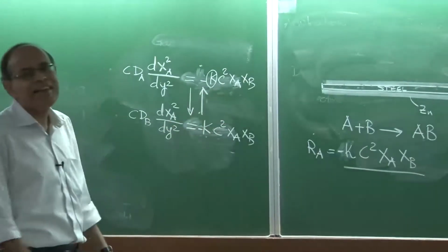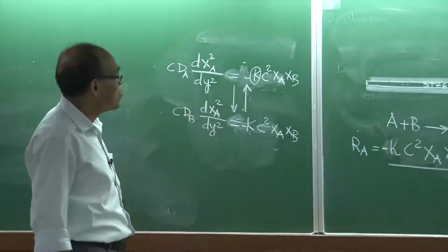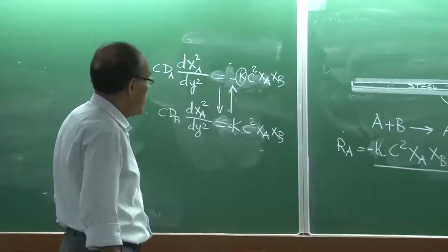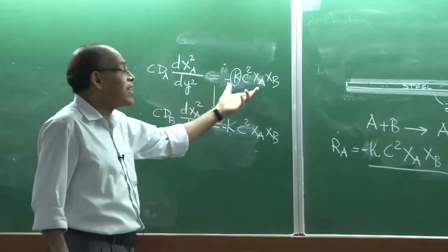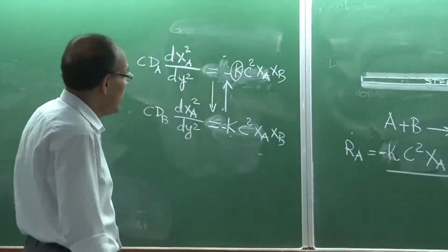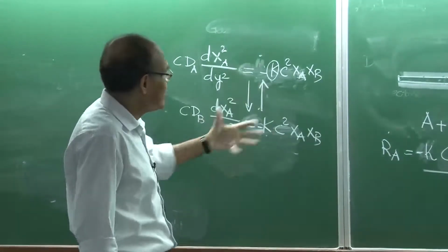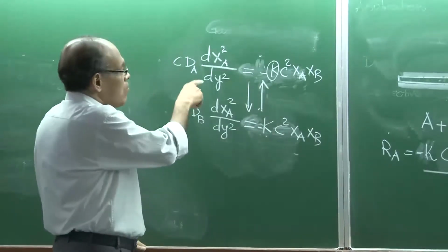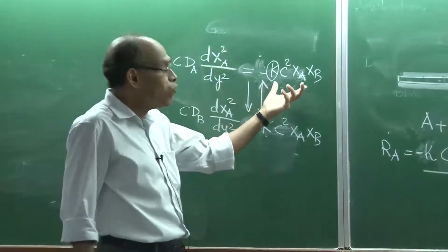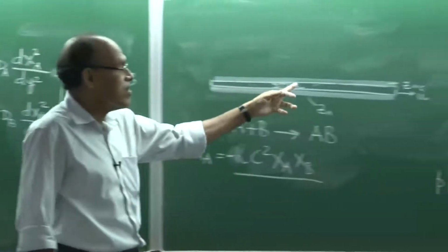These solid state reactions are very, very slow actually. They are as slow as the diffusion process, so they may affect the concentration profiles. These reactions may also be associated with some kind of heat generation or heat consumption, depending on the specific chemical reactions concerned. What it means is that within the domain of diffusion there is an influence on the concentration profile because of the chemical reactions.